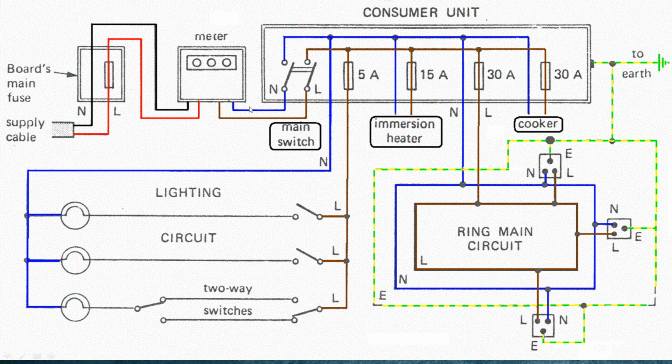So remember, we said that all fuses and switches are connected to the live wire side. This one here, the brown one. So where you find a fuse, the fuses are connected to the live wires. Even switches, the same story. And we said these appliances are always connected in parallel. If you have, for example, these bulbs, you always connect them across the live and the neutral.